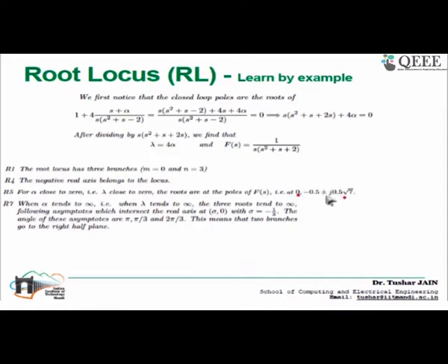Okay, we add these poles, and once we add them and divide by 3, it will give me sigma equal to 1 minus 3, which is basically an asymptote. The angle of these asymptotes you can compute by the formula also given in rule number 7, which is given by eta k equal to (2k minus 1) times pi divided by n minus m.